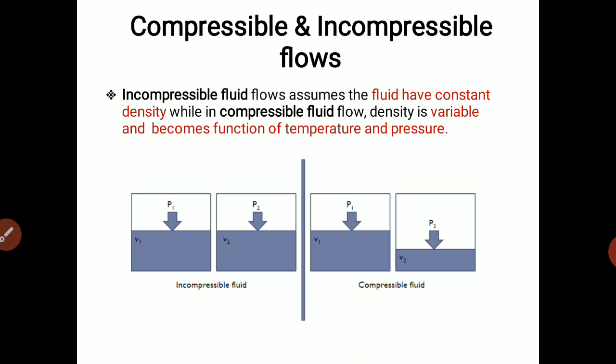It is an example of compressible flow. And what is the example of incompressible flow? So just take hydraulic problems, flow of gases in machines like fans and blowers. So these are incompressible flow, where density is constant in incompressible flow and density is variable in compressible flow. So that is the main difference between compressible and incompressible flow. Just remember density. In incompressible flows, density is constant, and in compressible flow, density is not constant. It will vary according to temperature and pressure.